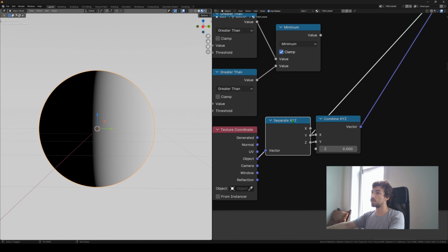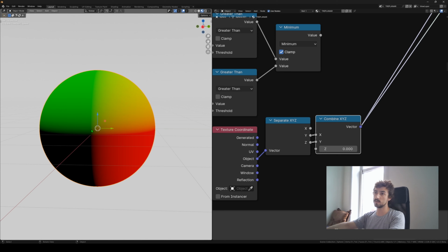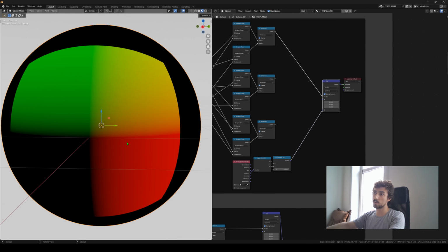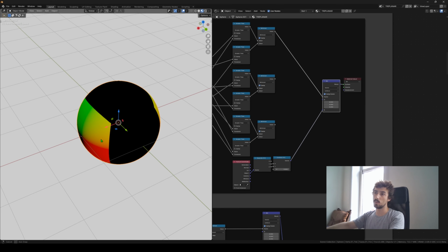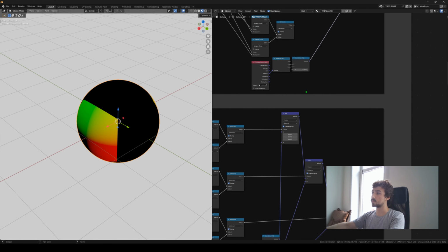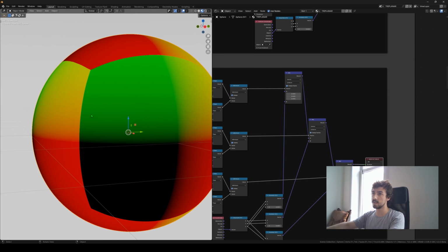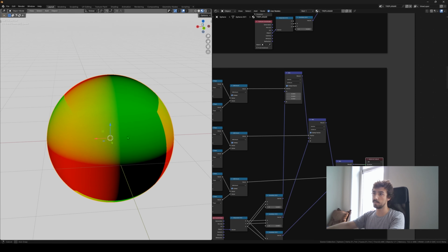And so we can just recreate, we can just isolate. In this case, there's a gradient that goes sideways, it's the y one, and one that goes upwards, that's the z one. So let's just combine them as if it was x and y. And that's creating us this UV coordinate that we just isolate in this square that we said was pointing mainly towards x. So again, we just duplicate the approach a few times to have it for x and z as well. And we start to have some nice UV spaces in every direction.